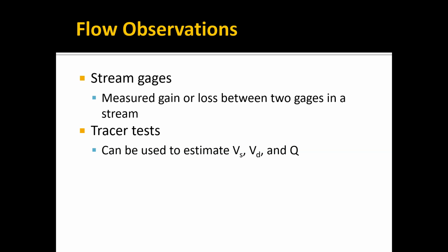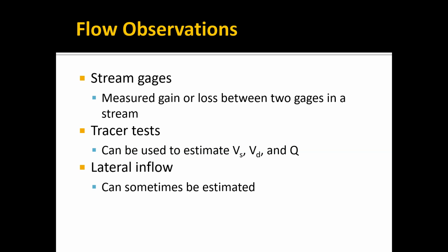And if you have a large area, and maybe it's not on your site, but someone has done a tracer test to give some kind of idea of the groundwater flow rate, that's better than nothing. And so again, if you do nothing more than come up with an estimate of a reasonable flow velocity, that is way better than nothing, because once you fix the Q, you've eliminated one of your unknowns, and the only unknown left would be the hydraulic conductivity.